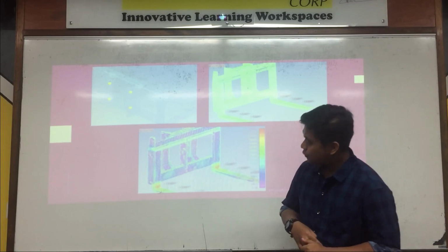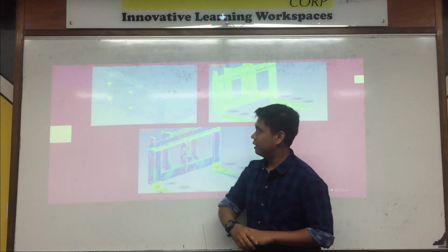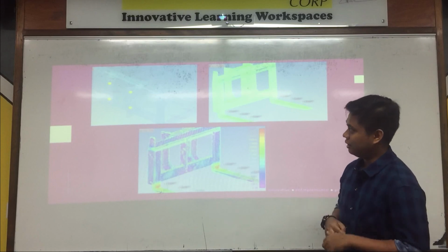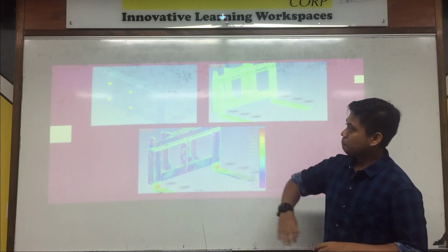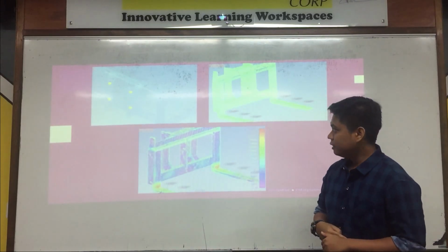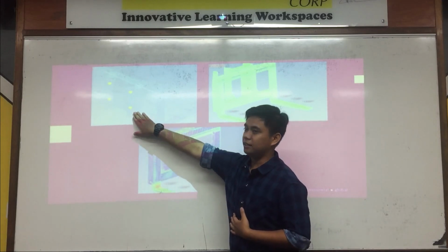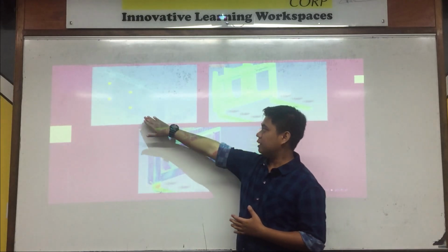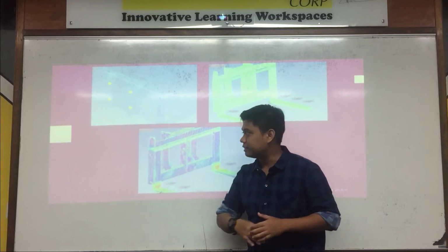So for the boundary condition, we just set for pinhole at the back of the front part of the fork carriage. So basically, the 4 pins will be fixed for the constraints. So it doesn't matter if we put a fixed constraint or pin constraint, because if we set it to the pin constraint, it still be the fixed constraint.